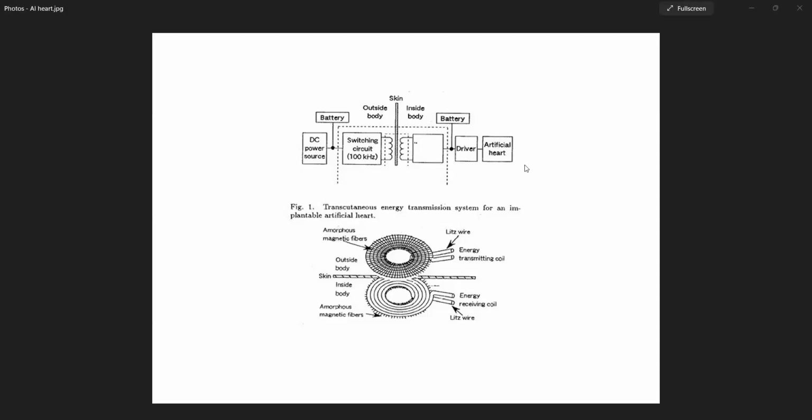So now my aim is to turn on this artificial heart. How we are going to give energy to this artificial heart is all about the working principle. The electromagnetic heart contains two rechargeable batteries which are connected to two different oscillator circuits operating at different frequencies. The first oscillator circuit is operating at 100 kilohertz, whereas the second oscillator circuit is operating at 100 megahertz, high frequency. So these two oscillator circuits create two magnetic energies which are operating at different frequencies.